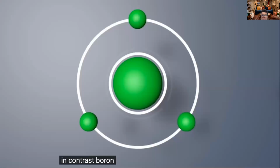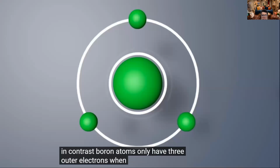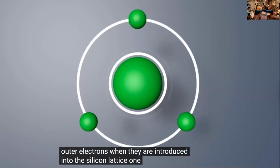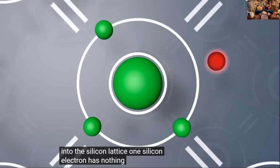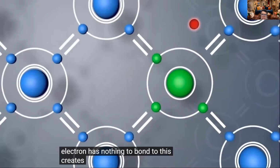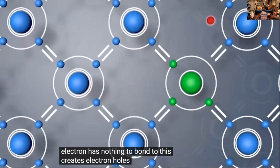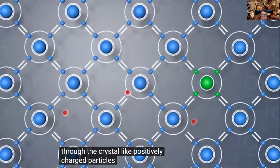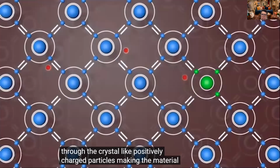In contrast, boron atoms only have 3 outer electrons. When they are introduced into the silicon lattice, one silicon electron has nothing to bond to. This creates electron holes. The holes move through the crystal like positively charged particles, making the material p-conductive.